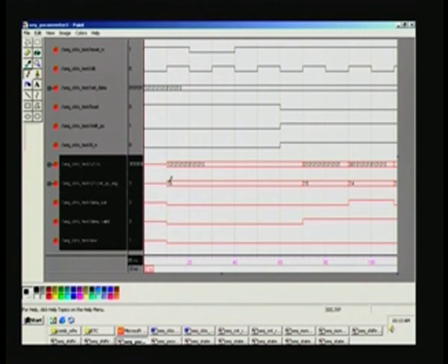Now, you need to send 16 bits, so it is initialized to 16 here, and every bit going out, this will be decremented, as you can see, going to 15 here, 14 here. Why a long gap is, we have first loaded this value by activating this high, and it goes low only here, and then simultaneously we will make the shift control high, so that with the arrival of the next positive edge of the clock, it starts and the counter starts decrementing, as well as it outputs the value. Data out is here. To start with, it is all 0 here.